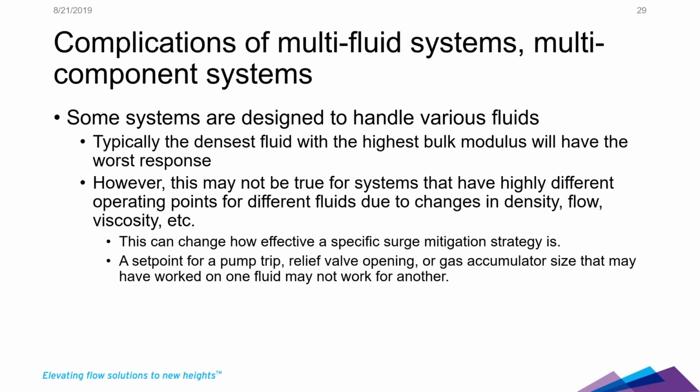And so as your transient is happening, it might not hit that set point until it's too late, until your transient's over, some sort of fast event happened. Maybe it didn't pop your relief valve because it had a higher pressure difference to go up before it popped that relief valve. And that pressure difference is kind of important. How soon that valve opens is kind of important. How soon your pump trips is very important.